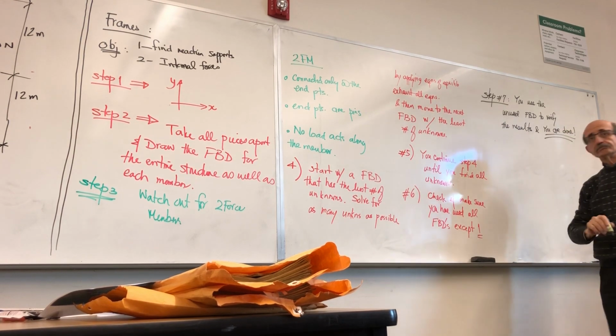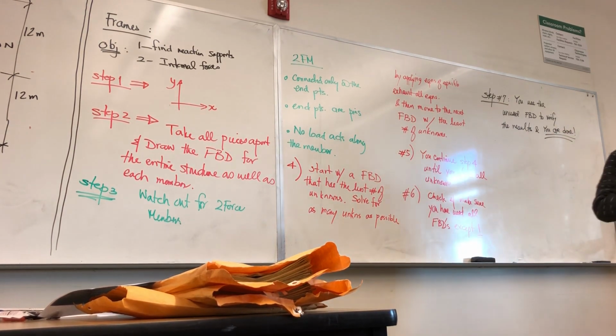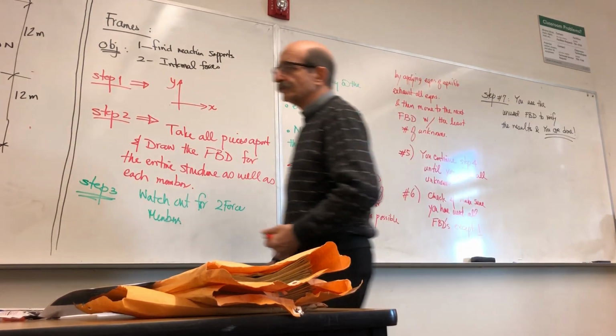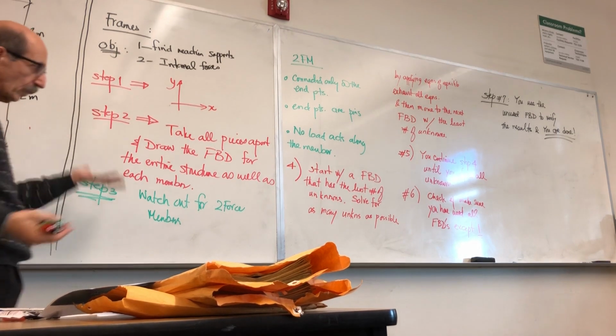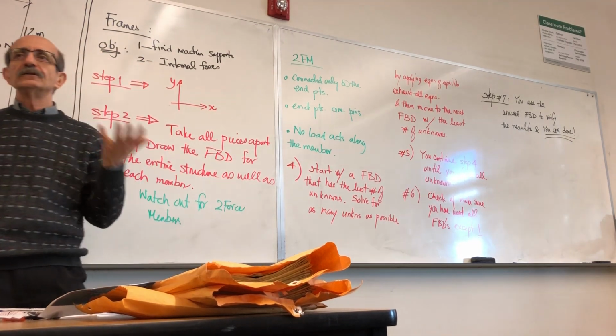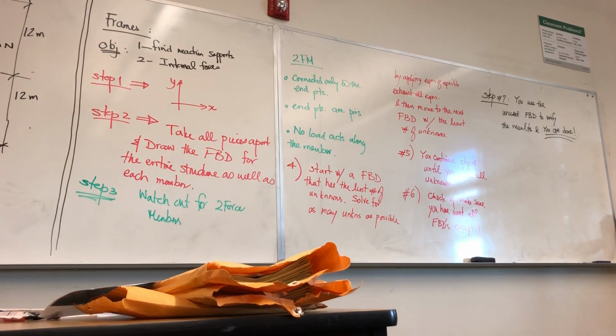If that free body diagram checks out, all the answers are correct. In other words, on that free body diagram you have all the forces because you found them from all the free body diagrams that you have already used. So put all those forces you found on it, and they should satisfy the equilibrium. If the summation of forces along X or Y or summation of moments does not turn out to be 0, that means you've done something wrong. You have to go back and check.